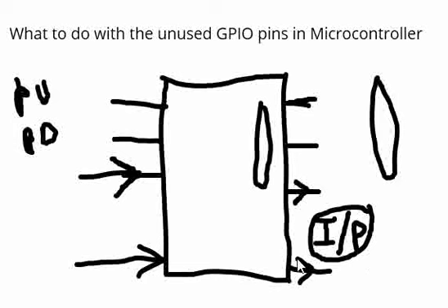You can leave it as is, because this is an output pin and it only tries to drive, and there won't be any input to this pin. There is less chance that it affects the operation of this IC. So output pins are not a problem. Unconnected input pins specifically are a problem which need to be terminated.